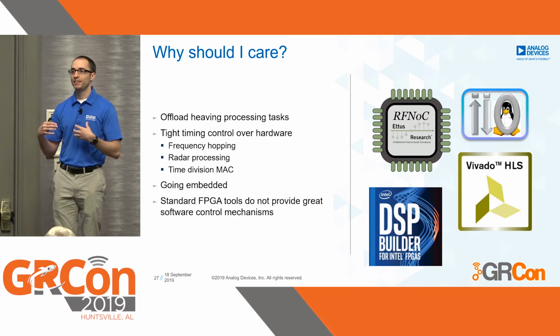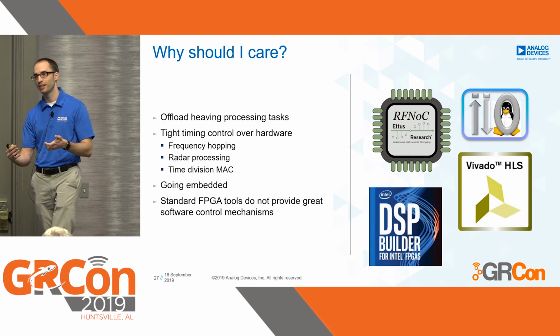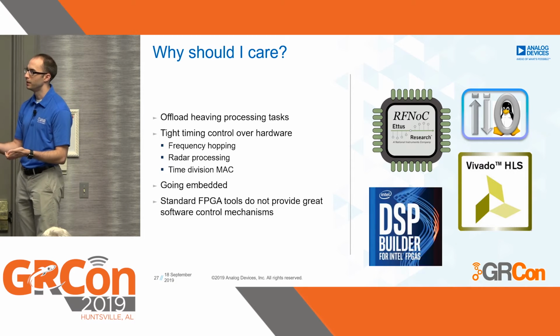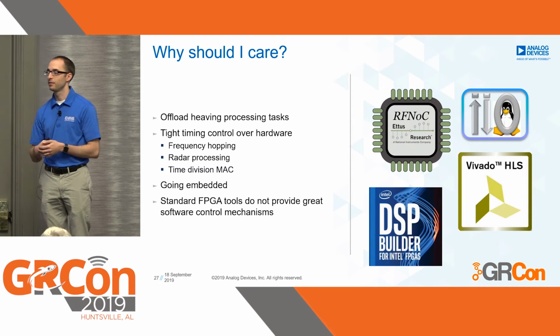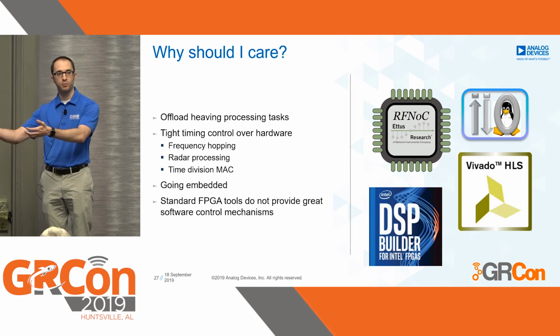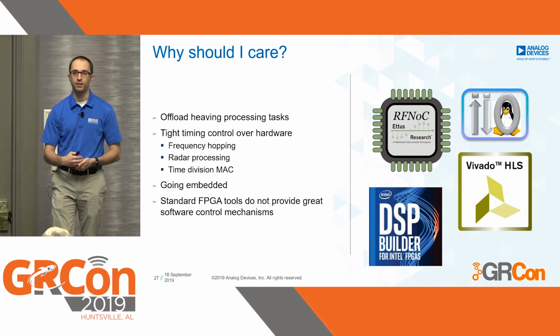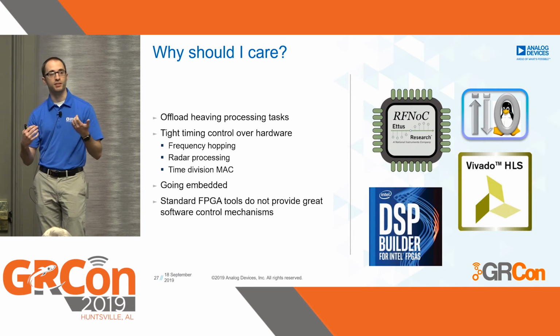However, I would say that the standard tools that are provided by a lot of vendors don't make it easy to talk to IP that you generate. Vivado HLS and DSP Builder are great tools. They get your IP on the board. They make it simple. But actually talking to that IP can be challenging.